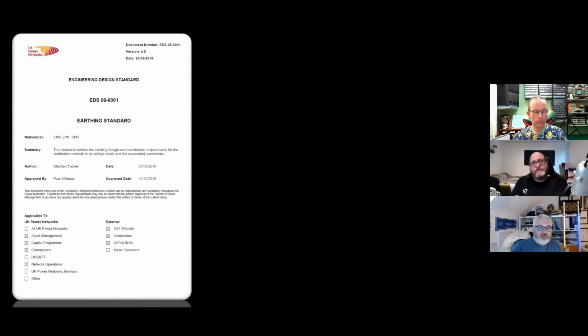I'm now going to use, we'll get on some photos and coding in a second, UK Power Networks as an example, my local DNO. They have their own method and means to comply with, say, G12. So it's very much a hierarchy of standards and how they interpret it. You've got G12, then you've got, say, their earthing standard, which they call EDSO 6001.